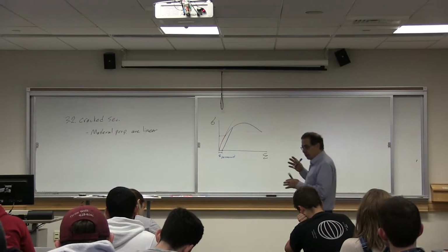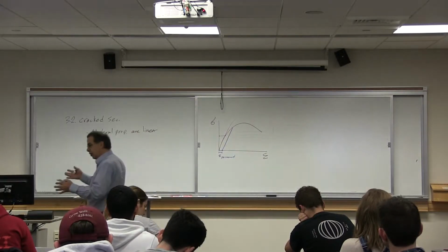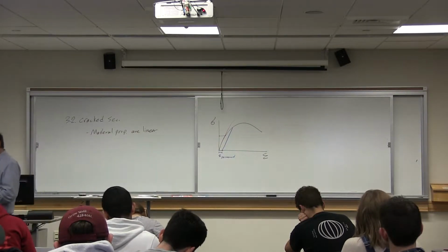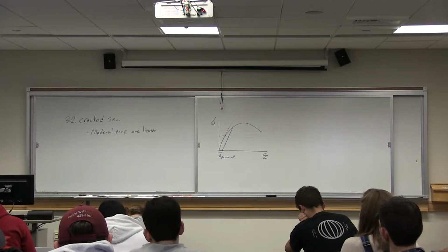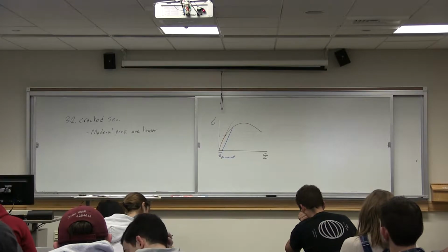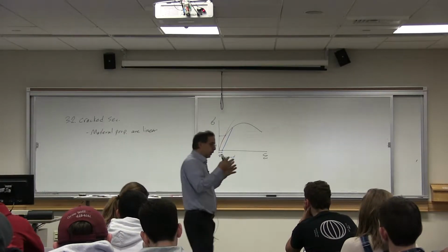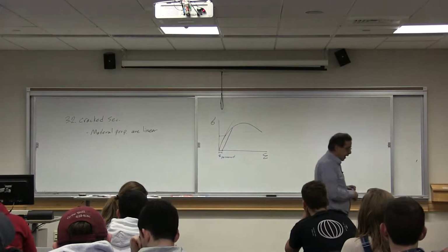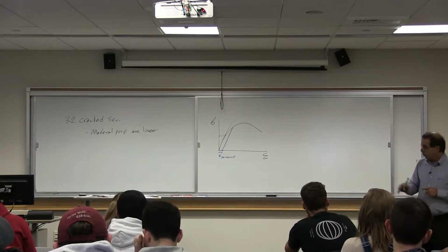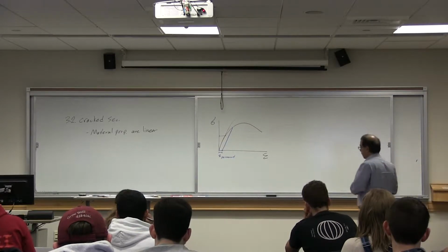We don't say that the section cannot take more moment. The section can take significantly more moment, and the stress can go significantly higher under exceptional conditions. Let's say, again, there is an earthquake someday. That's okay. The structure would move and be damaged to some extent. What we are talking about here is under service conditions.